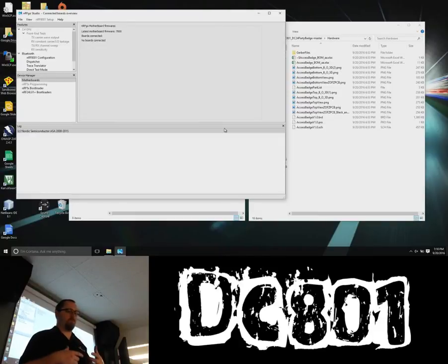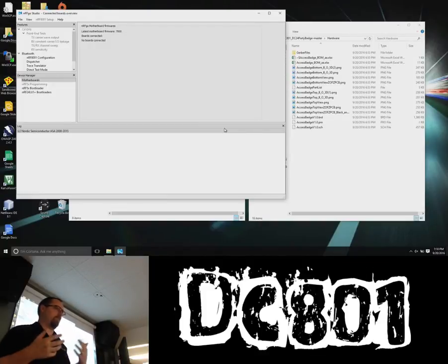Nordic has some nice tools too. They have Nordic's tools that you can download for your smartphone as well that will help you do development with the BLE. It has different programs within it. Because you can have proximity with your BLE device, you can do the Eddystone or iBeacon. You can also make it act like a mouse or act like a keyboard. There's lots of different things you can do with the BLE, and the tools that I'll go through will help you do it. There's a lot of example code for it that you can play with.